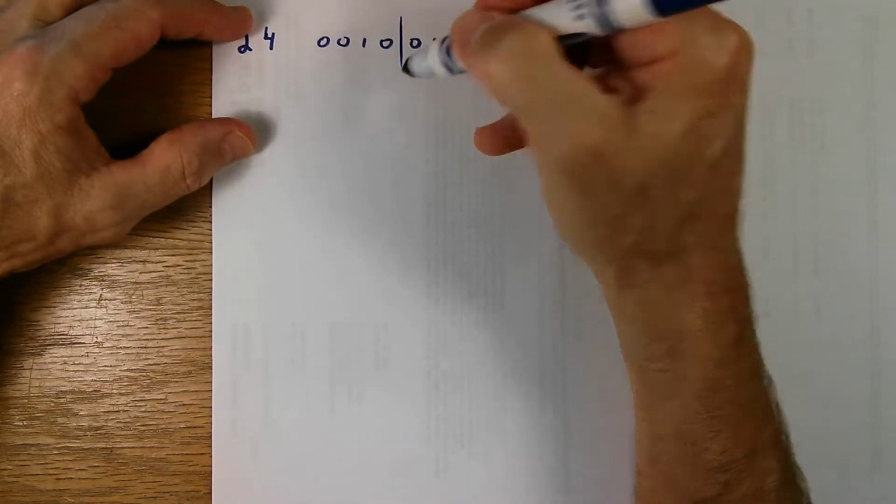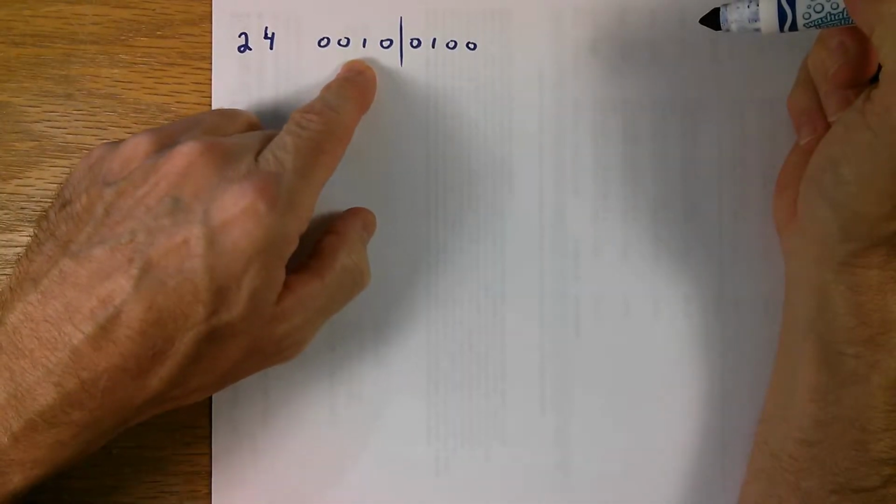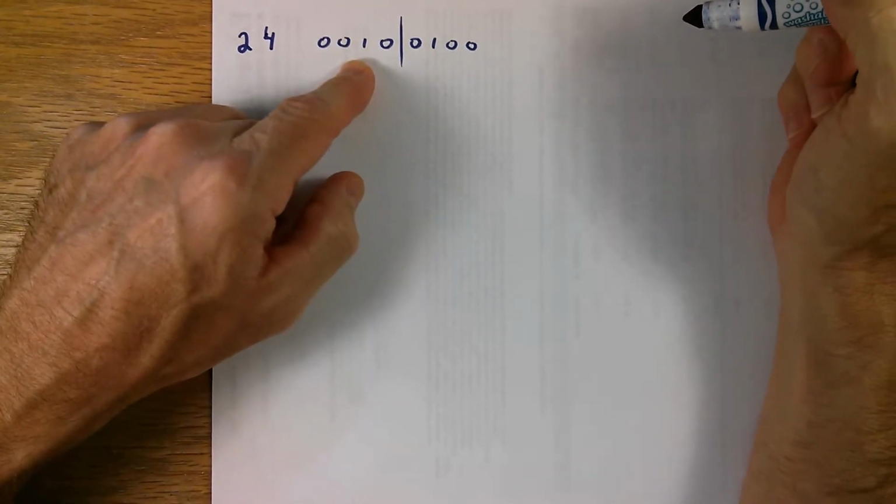Now you can combine operations that I just talked about to extract parts of a byte. I briefly talked about the shift operations as being a multiply and divide. Left shifting by 1 bit multiplies by 2. Right shifting by 1 bit divides by 2. But for example, I've got a byte here that contains 2 binary coded decimals, a 2 and a 4, like this. And I want to have access to this one and treat it as a variable all by itself.